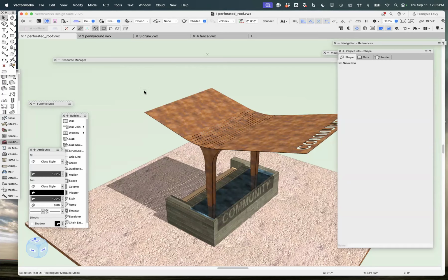And then you can see that it's given me a NURBS surface. I'm going to group it and go into the group just to be able to show it to you. So that's it. However I get that geometry, whether it was an extrude along path, that was probably just a line that I made the profile of that roof plate steel and then extruded it and then shelled it to make it the correct thickness. But however you got there, I went ahead and extracted that face. So all that just to demonstrate how you would get the NURBS surface along which you're going to do the array. Let's go back to the array itself, edit the solid.